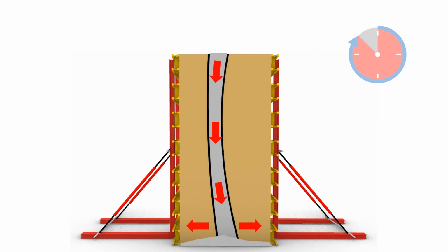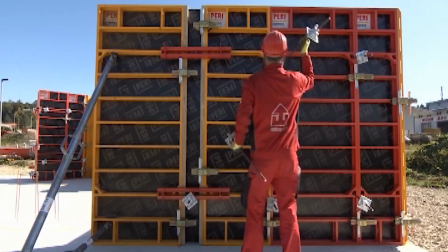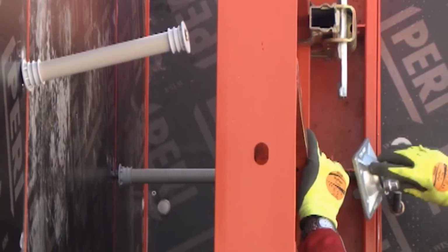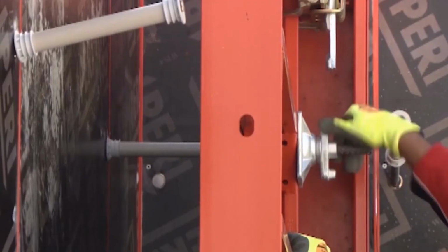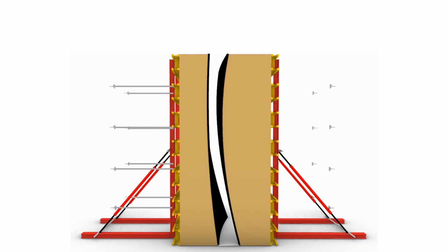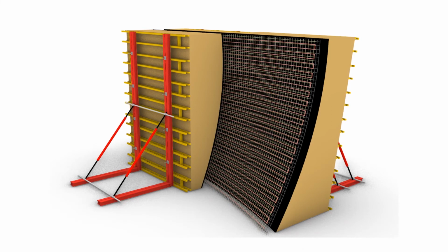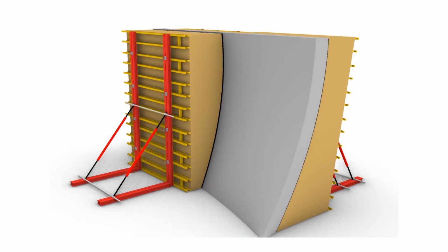The construction company solves this problem as follows. The bolts and plastic cones are used when assembling formwork. Insert tie bolts at regular intervals, pass the cone, and fix the formwork. This prevents the formwork failure. After tie bolt installation is complete, the concrete will be cast.